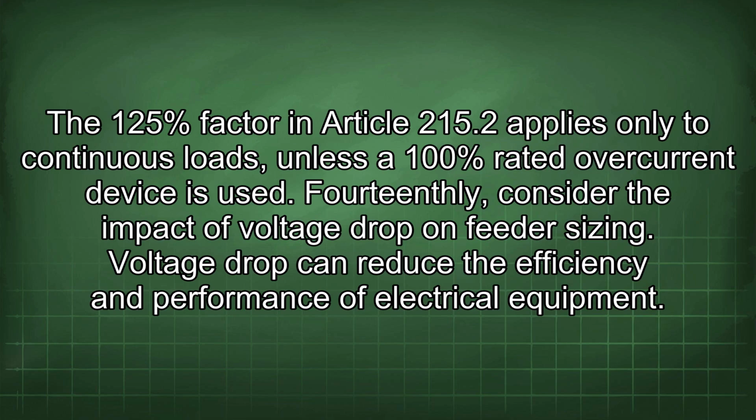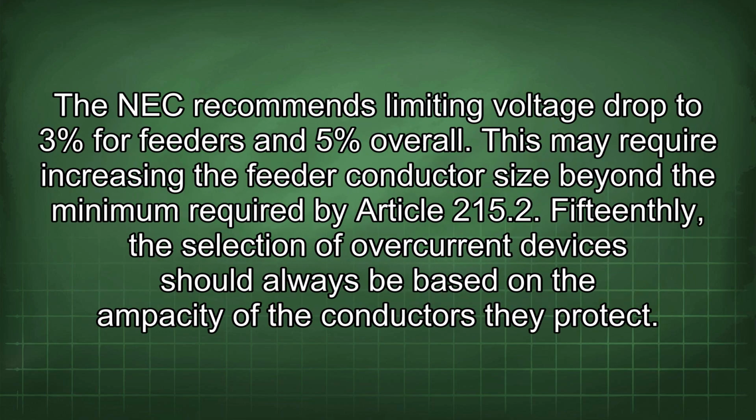14thly, consider the impact of voltage drop on feeder sizing. Voltage drop can reduce the efficiency and performance of electrical equipment. The NEC recommends limiting voltage drop to 3% for feeders and 5% overall. This may require increasing the feeder conductor size beyond the minimum required by Article 215.2.